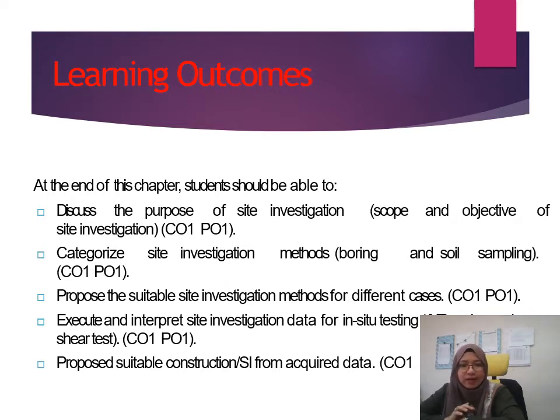There are various types of in situ testing, which means you can get the result or the soil properties directly from site. That is field testing, or in situ testing. Or you can also take the sample and bring it to the lab and conduct testing. That is laboratory testing. That testing is also included in site investigation. And the last one, propose suitable construction from the acquired SI data.